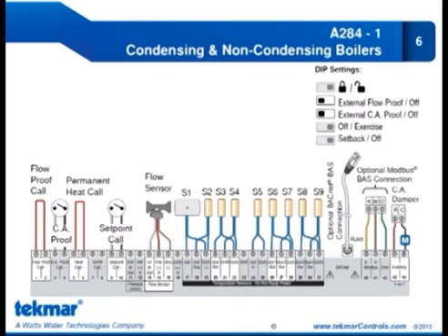They hook the 423 up to the 284 via the EMS input in the 284. Then they would connect the gateway to the actual 423. So now all the information connected to the 423 will be accessed and displayed on the web-based gateway. The 284 information, however, is not going to be displayed on the gateway.